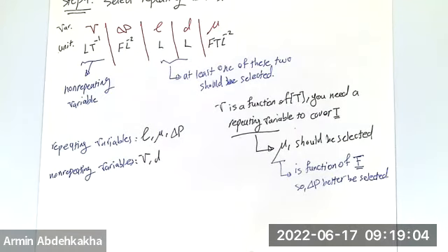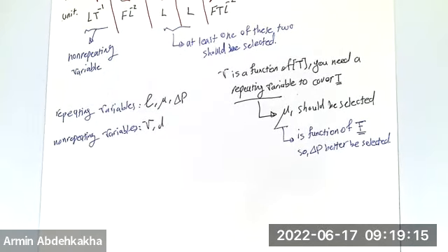If it's one of the Pi terms or the Reynolds number, it's better to select those parameters in a way to get that Reynolds number. Because, why? Because you can find thousands of experimental studies done before, and you can compare yours with them, because they are reporting the Reynolds number as a parameter that they are testing, okay?